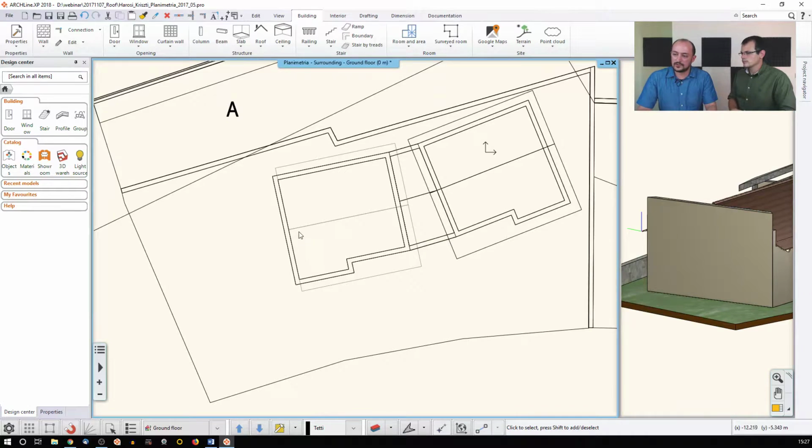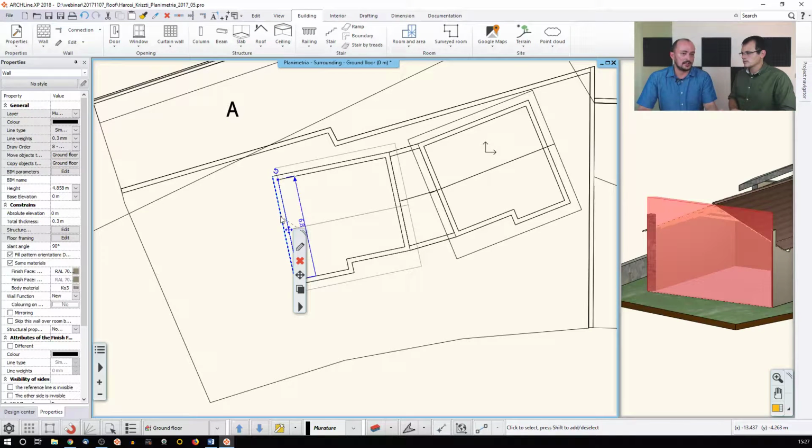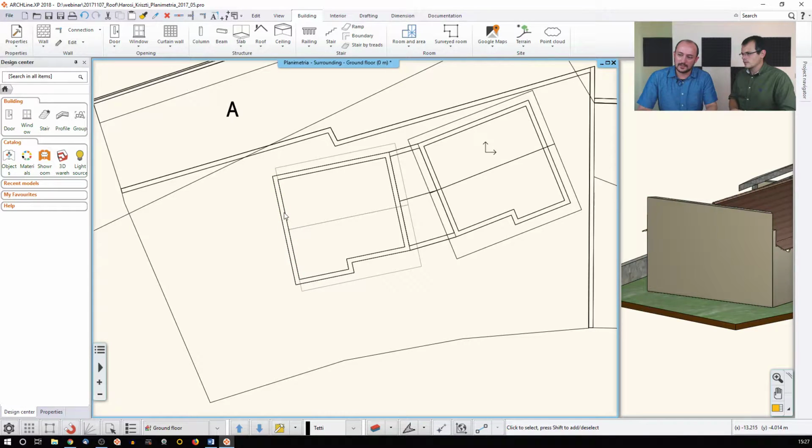So there is a solution to that, and it's kind of a uniform solution for all of the walls and all the times when you would like to change the shape of the wall, and it comes in the local menu of the wall. Now keep that in mind, it's important on which side of the wall you click. So if I click on this side of the wall, I can edit this side of the wall. If I click into the internal side, then that's a different shape.